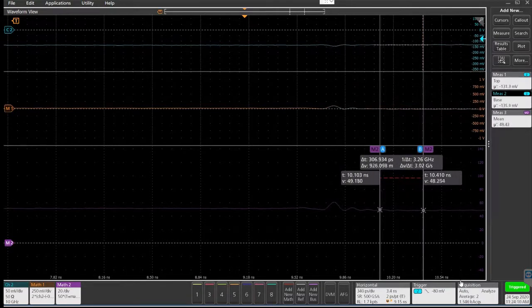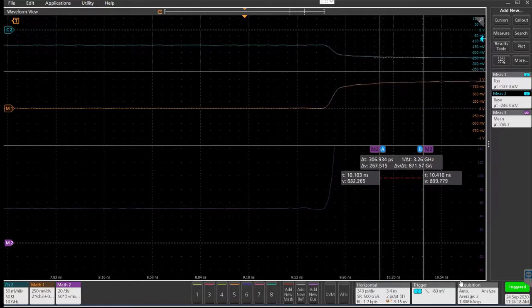Make sure we got on there well. Yeah, now we're placed better. That's 48.5 ohms. There's about 2 ohm difference between the two traces because of the solder mask.